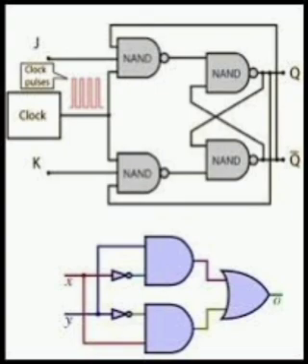Half adder means sum S equals A bar B plus A B bar, that is A XOR B, and carry C equals AB. The total number of NAND gates required to implement a half adder is 5. The total number of NOR gates required to implement a half adder is 5. To implement the half adder circuit with the minimum number of logic gates, if we have all gates except XOR and XNOR, it is 3. The total number of 2 to 1 mux required to implement a half adder is 3.